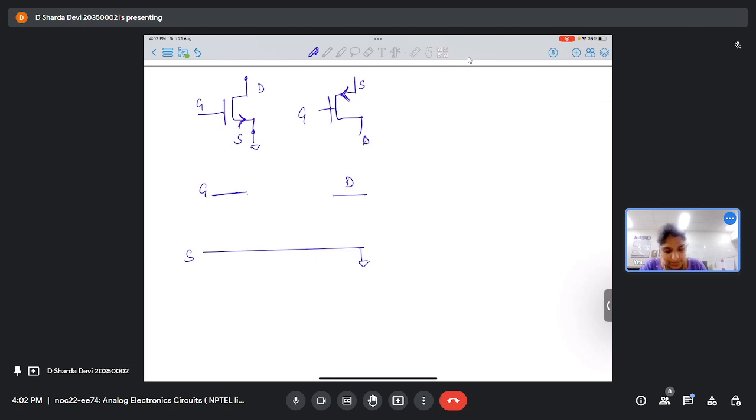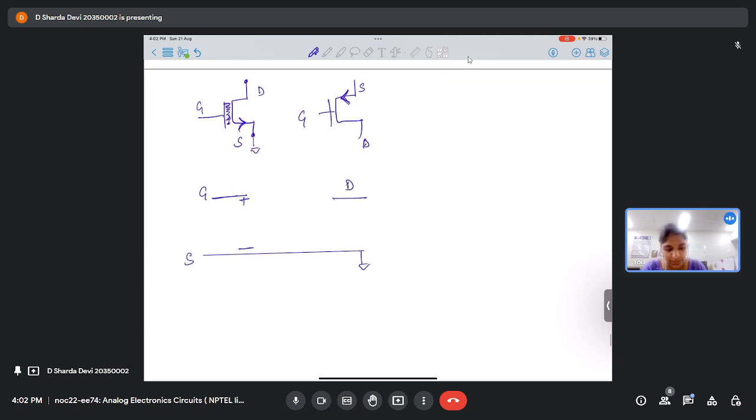that there is an isolation between the gate and the body of the MOSFET. So between G and S, the resistance is actually infinite because of this insulator. So if it would have been a BJT, here we would have replaced it with a resistor. But since here we have infinite input resistance, we simply keep it open and it becomes VGS. This is clear? Yes, ma'am. Okay.